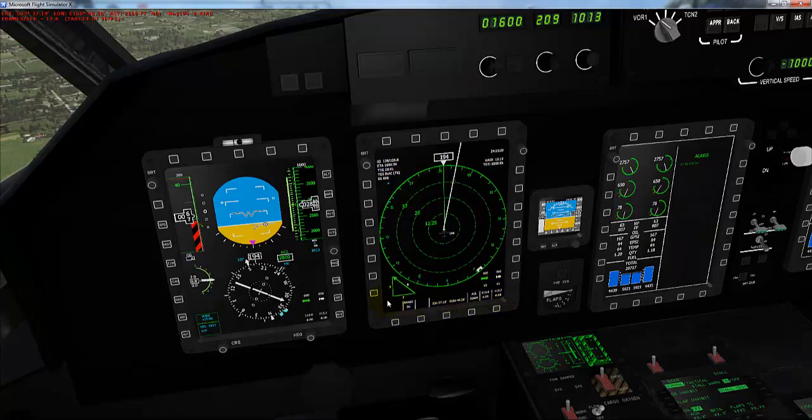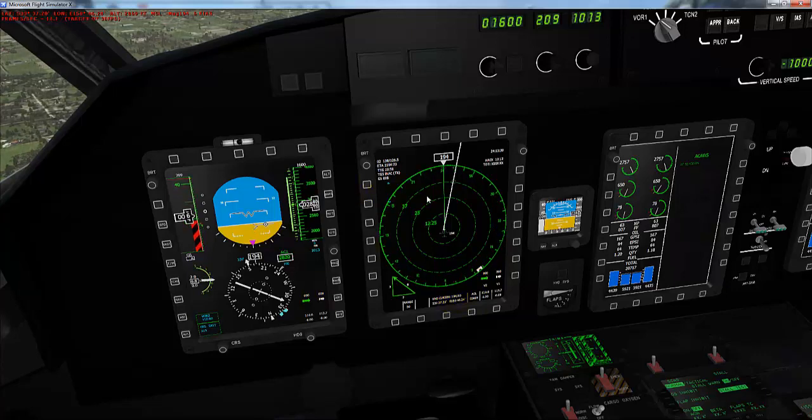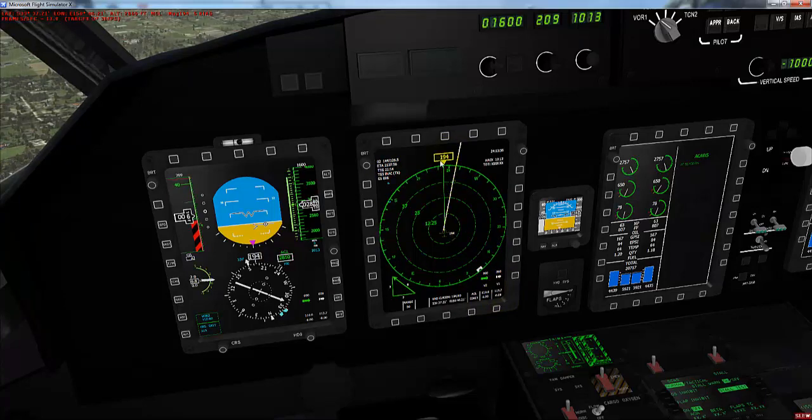Across the bottom you have a number of different information, including the current radar mode, range, your current location in lat and long, the radar cursor position in relation to your aircraft, your current AGL, and again your nav sources. You'll also notice this is showing your track here, and this shows your true bearing.